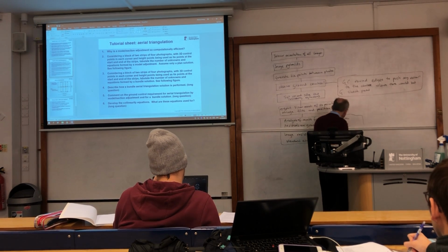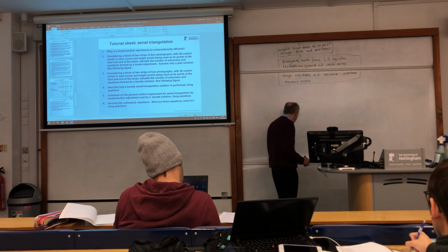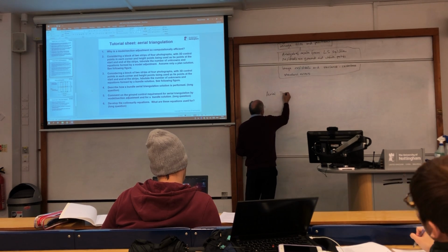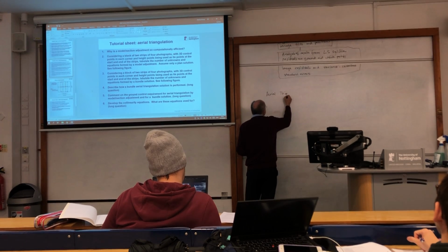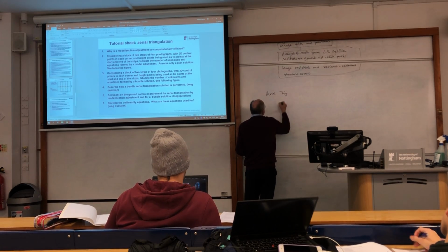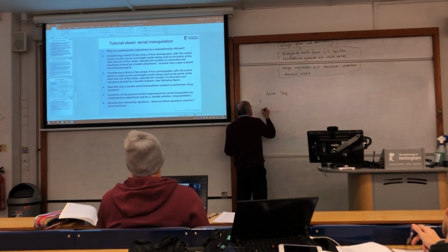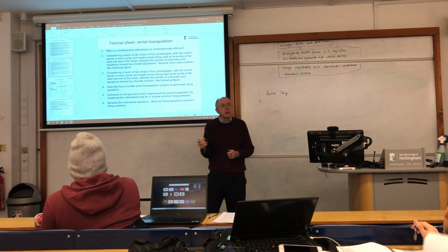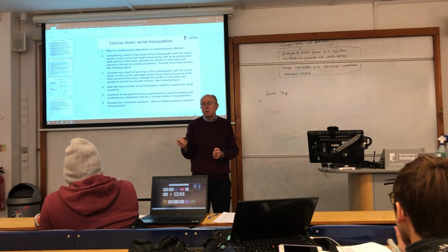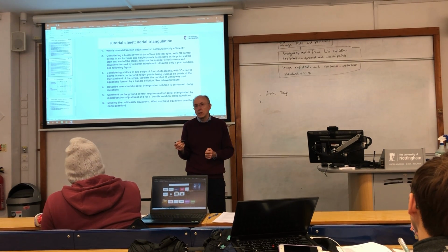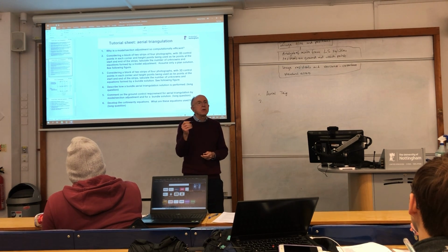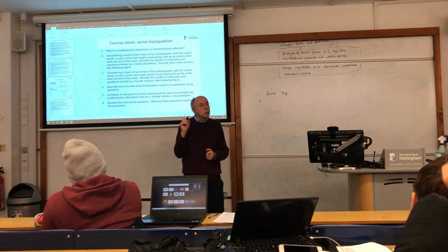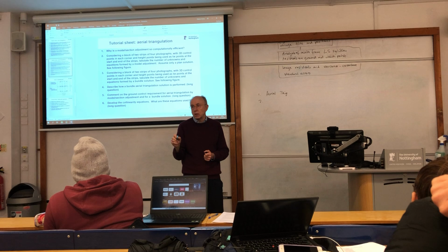Well, actually, let me just jot them down over here, just so you've got an idea. So we've got them for aerial triangulation. The second thing is, those of you that did the practical exercise, when we showed you in the demonstration that we've generated the stereo model, it is maintained in the software by real-time use of the collinearity equations.